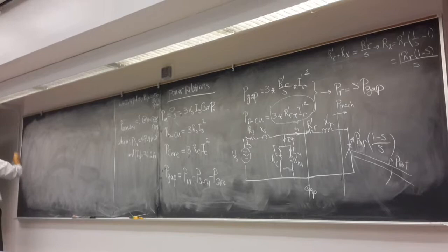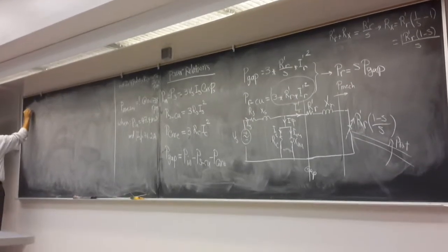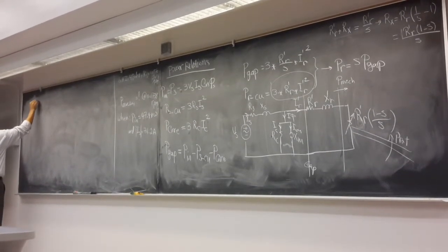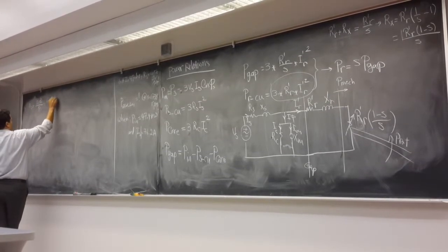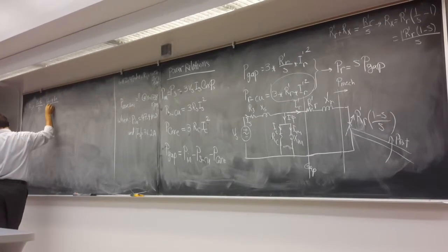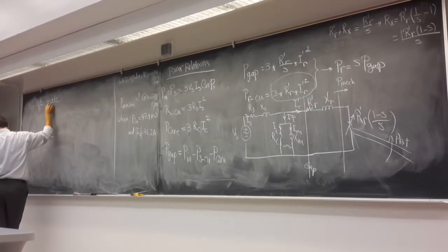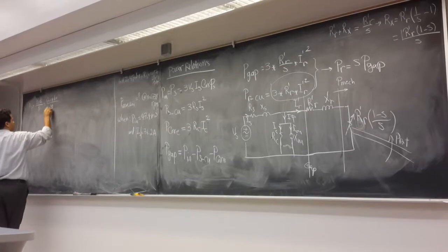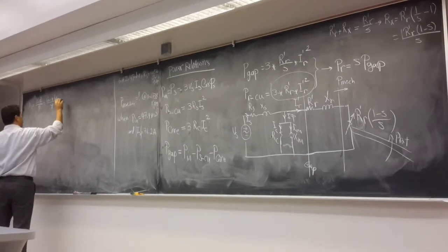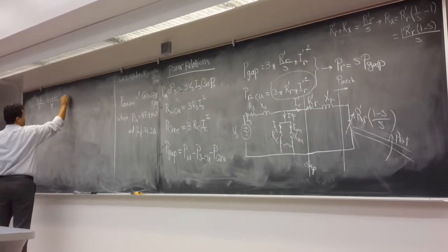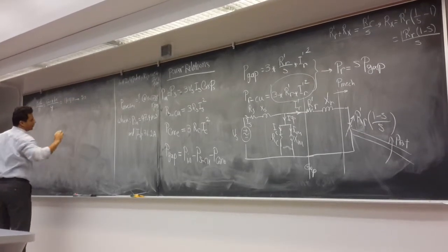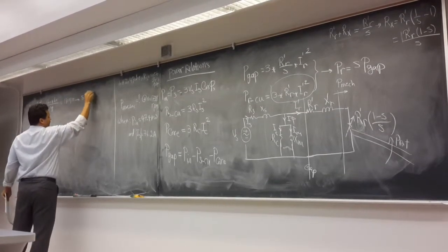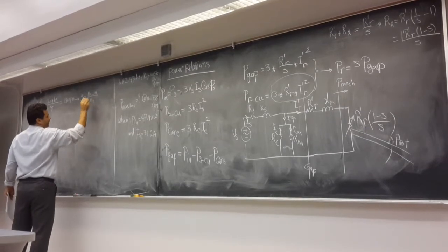First, let's calculate the NS. How much is the NS? 120 times 60 hertz over how many poles? 4 poles, right? So basically, it's going to be 1800 RPM. How much is the slip S? It is NS minus N over NS.